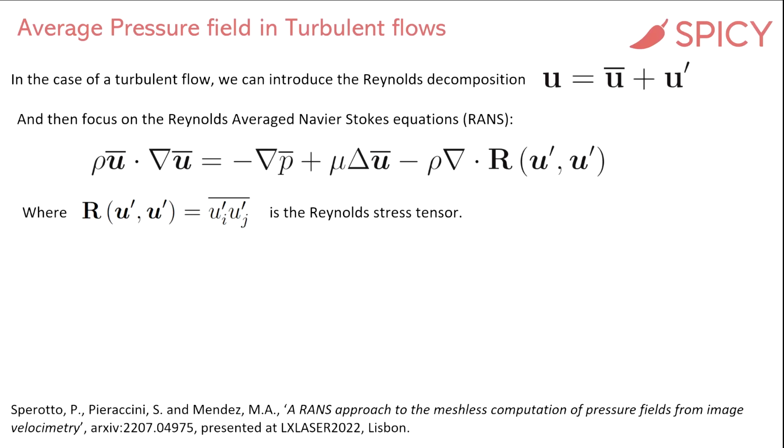They can be computed experimentally, especially from PTV, and Manuel Ratz will talk more about this in the last video of this course. But assuming that we have found these Reynolds stresses and we have also a good regression using radial basis function of these stresses, then we can easily compute the divergence, or we can easily compute this term in the equation.